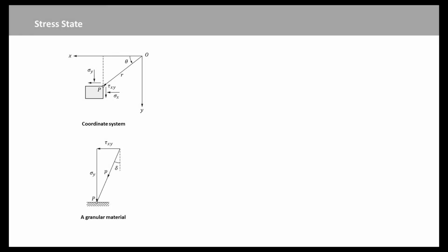Let us now consider the limiting equilibrium of a medium bounded by the x-axis, which is free from pressure and inclined to the horizontal at an angle delta. The stress state set up in the body will be called a simple stress state. We shall consider the equations which define the limiting plane equilibrium of a granular medium, using an ordinary system of rectangular coordinates x, y, and considering, for generality, that the x-axis is inclined to the horizontal at an angle delta.